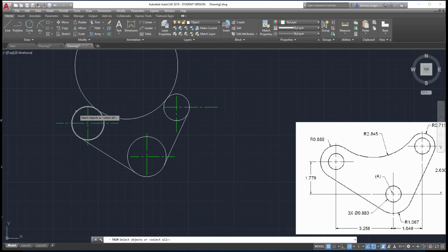So the cutting edge is actually the two circles, because the bigger arc, in this case the large circle, touches the two smaller circles, and so those happen to be the cutting edges. Once you've selected the objects of the cutting edges, and here's the key component, on the trim, on the extend, on the rotate, on the move, on the copy commands that we'll all be looking at, you have to hit the enter key after selecting objects.